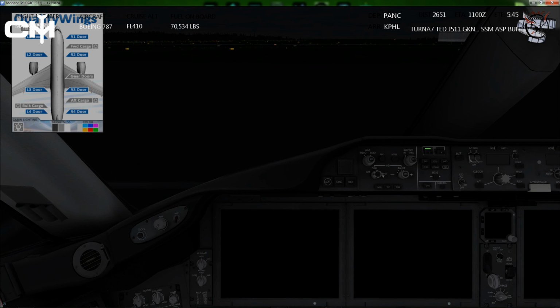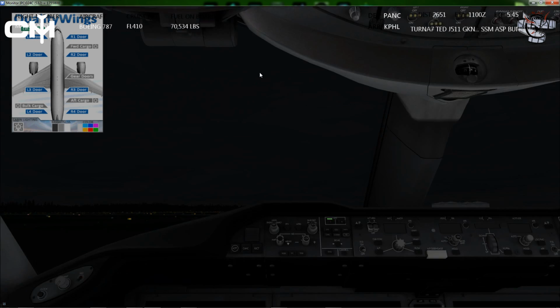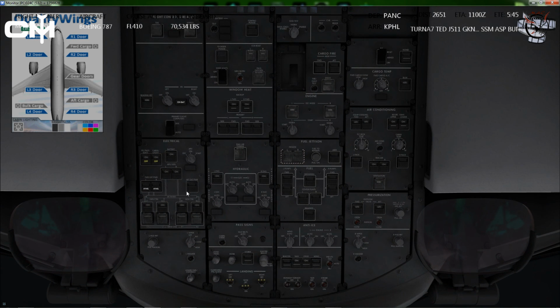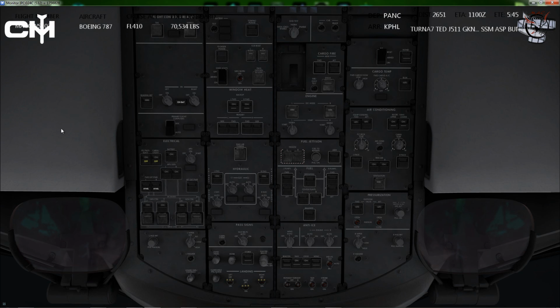And so what we want to do is get external power on the aircraft as quickly as possible so we don't burn through that. So just pop up your Quality Wings control panel by clicking here or the alternate button on the overhead. Flip on the external power, and I'll turn that button off up here. It's the aft external power that turns it on and off, and now you can see we've got our external power available. So click on that, bam, external power on the aircraft, and we're not burning through our battery.